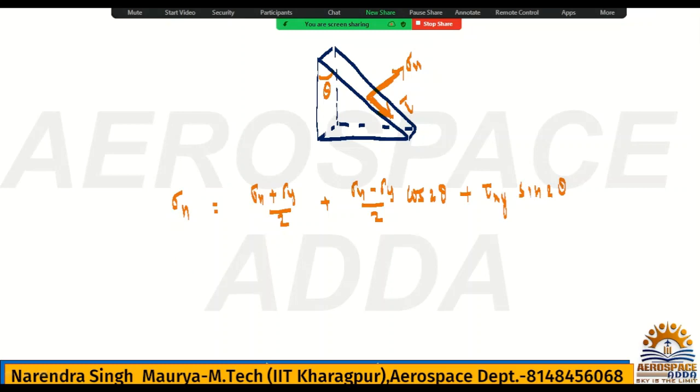This was the normal stress on the oblique plane. And what is the shear stress you had calculated in last class? It was sigma x minus sigma y by 2 sin 2 theta, and here this is the multiplication. I think in the previous lecture I had made a mistake. It was plus, but it should be product only. Minus tau xy cos 2 theta. Okay, this was the formula.